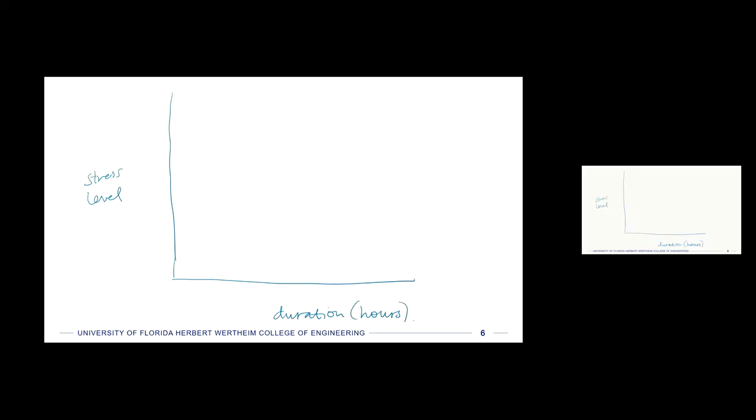Okay. And they call this mechanical acceleration, and they say that it's done at increased stress levels, but really it's done at increased strain levels. As I said, it's a stress relaxation experiment. So the first thing you do is crank it up to a really high strain and then just leave it there. You don't change the deformation. Whatever you put it at, you hold that distance constant in the experiment. So you start at some really high level of stress, and then eventually that stress will fall off over time as the stress relaxes out to some test duration.